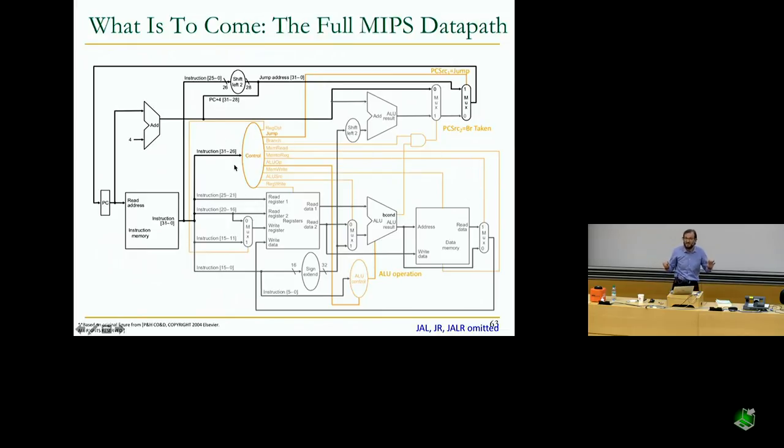These all are orchestrated based on the instruction that you're executing currently. Whether you write to the register file and whether you write to memory, read from memory, this is the memory write signal and this is the memory read signal. So all these control signals control how the data should be operated on based on the specification of the instruction that you've fetched over here. So there's no magic here.